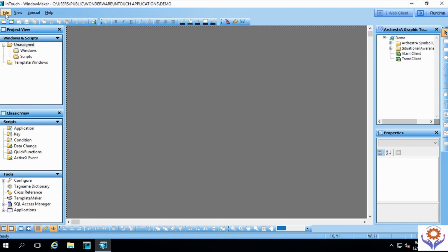You can add additional IO servers, but after that, Aveva created the System Management Console (SMC). From there, you can add your application driver. It is available on the internet. You can download it and add those IO servers. Let me check, maybe I added some IO drivers.